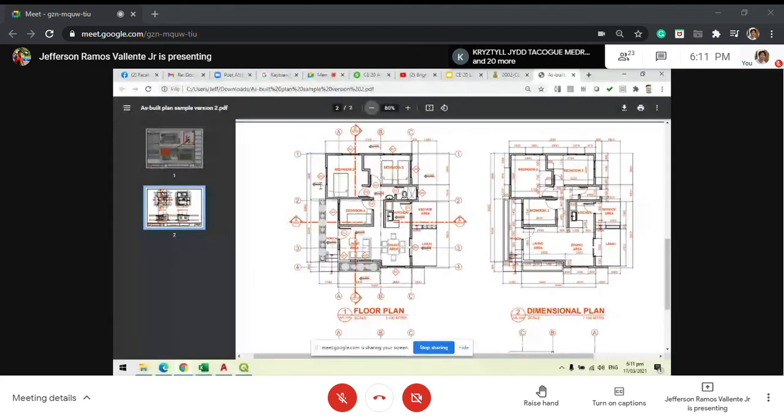And then you can also indicate the distances like this one. This is 3,600. This is in mm. So in the measurement, I'd like everyone to also use mm. We can draw good, smaller whole numbers if we use mm. If you use meters, sometimes you get decimals like 0.5 meters, which cannot be properly implemented in the field. So just use mm as a measurement.